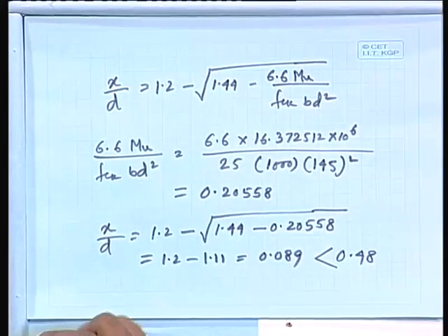In all the cases for a slab you will find we are using only 3 formulas. Formula number 1 is Mu equal to 0.138 fck b d square. Whatever effective depth you get computed, on the basis of that we can provide the overall depth also, and then we can find out the effective depth provided.